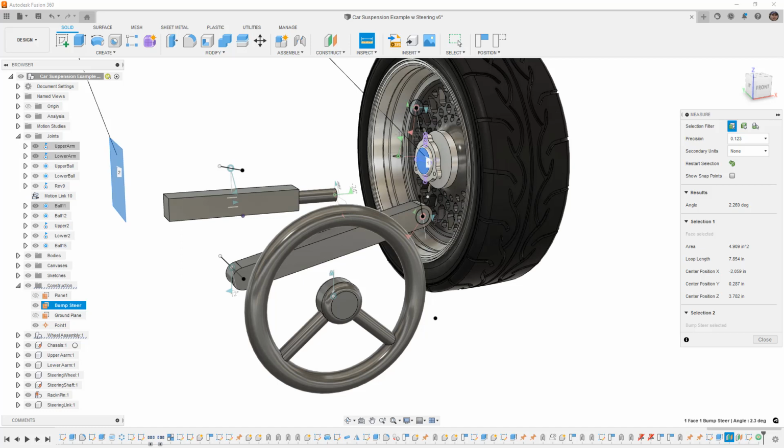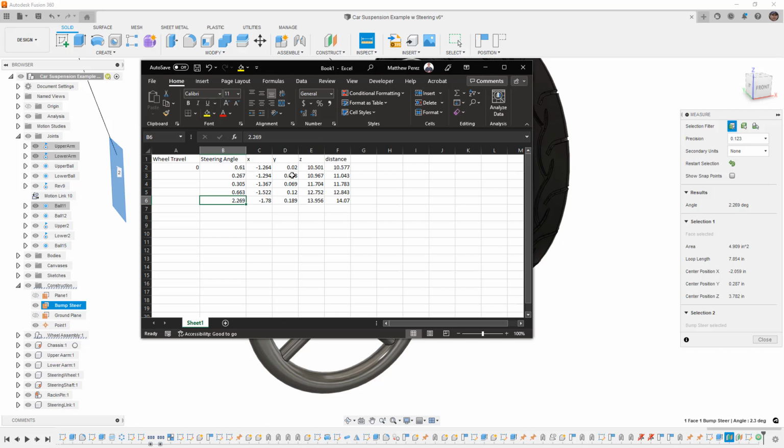So as we're looking at those values, we have got our XYZ, which again is good information to understand, especially if your lower and upper control arms are offset or your spindles are at an angle, if you've got some camber and some caster built into your suspension, you would want to track how these things are moving. Keep in mind, again, we're talking about the steering locked in a straight position. You could do this exact same thing by turning the wheel or moving the suspension a certain amount, capturing that position and locking it, and then moving it vertically through the travel. It just takes a lot of time to plot these numbers.